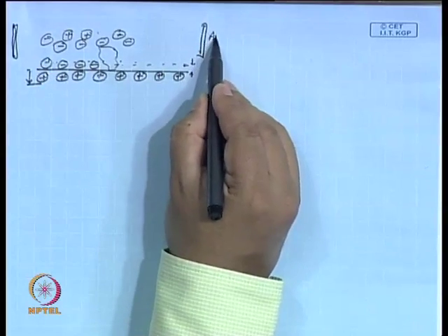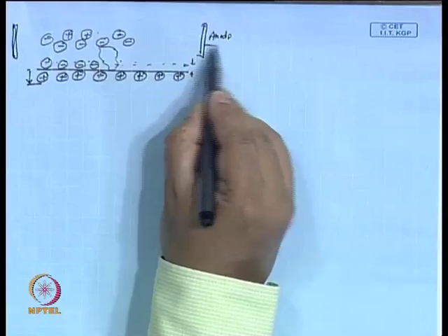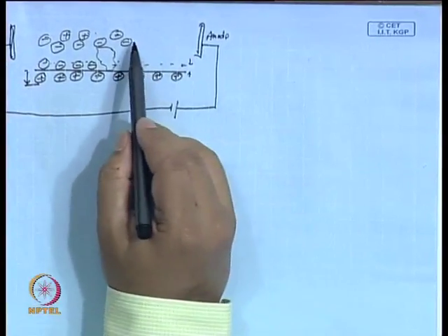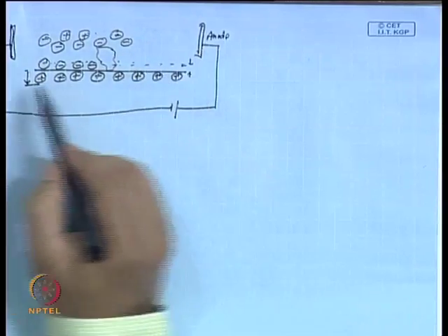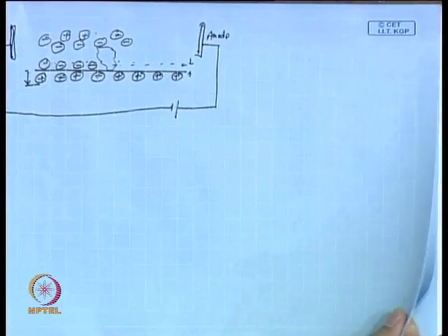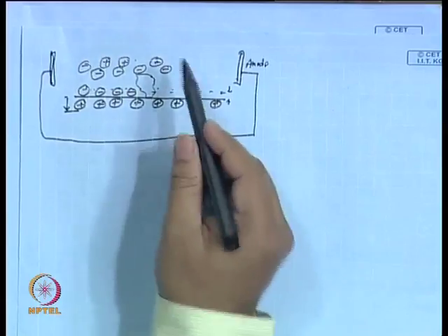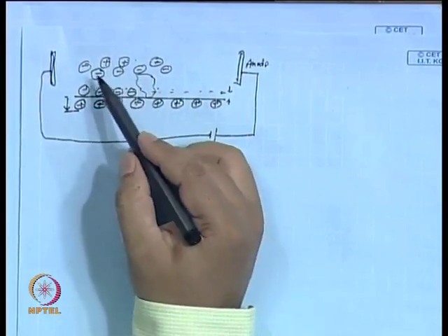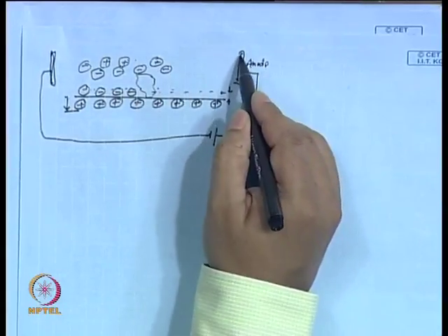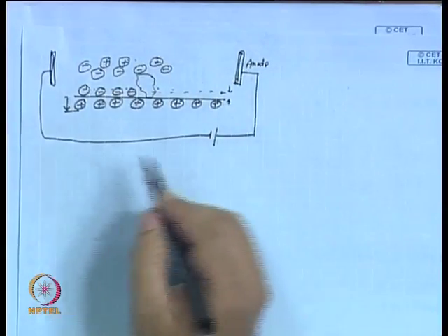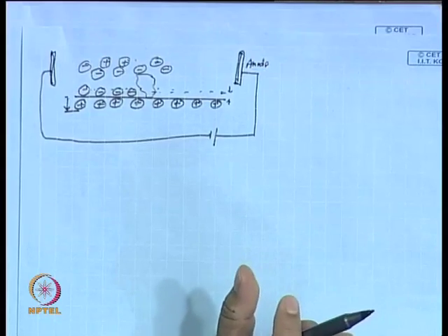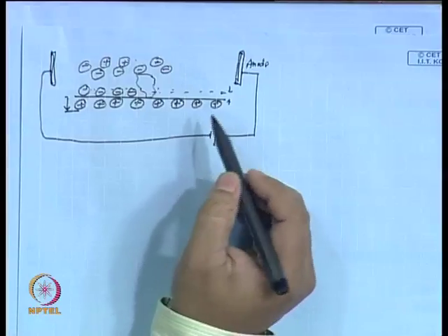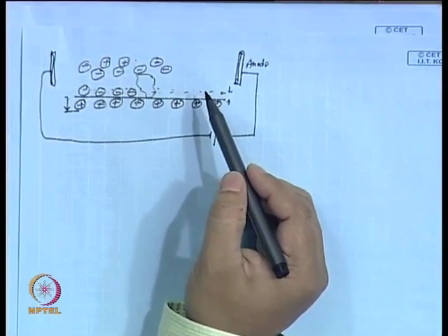If this acts as an anode, that means if you put a voltage across these two electrodes, then automatically these negative charges will be pulled to one electrode, and by that way there would be ion drag possible on the fluid existing in the channel, and the fluid will start moving, because as I said in the earlier class, in the Navier-Stokes equation there would be a body force term arising from this ion drag. This is something which we referred to as electro-osmosis.